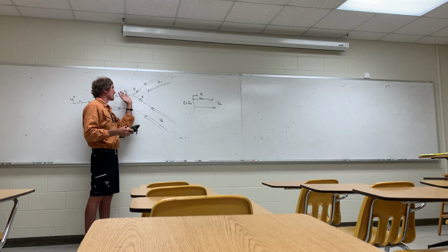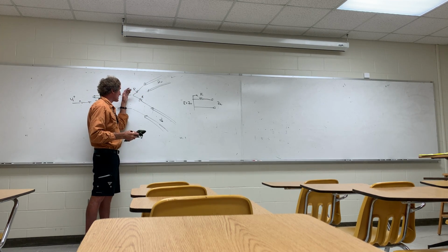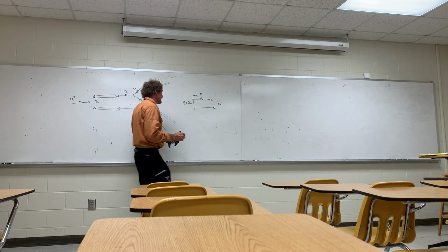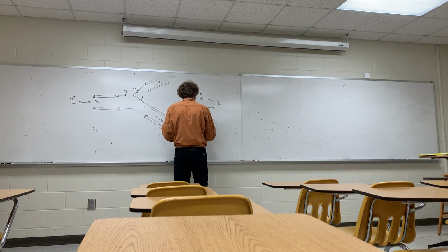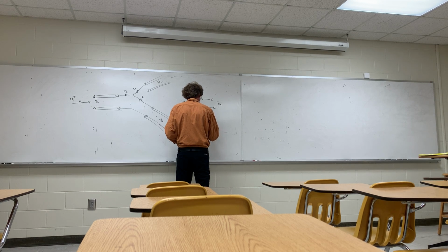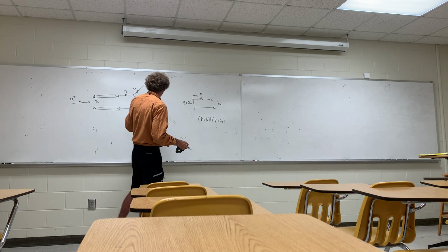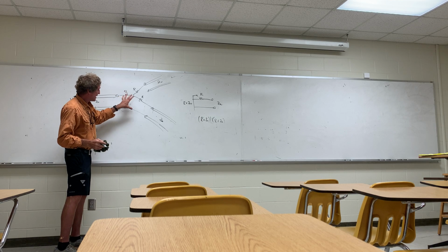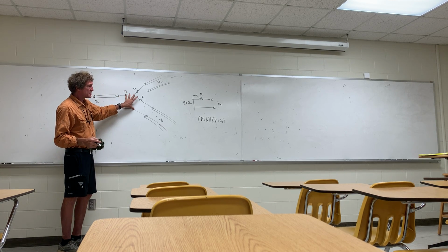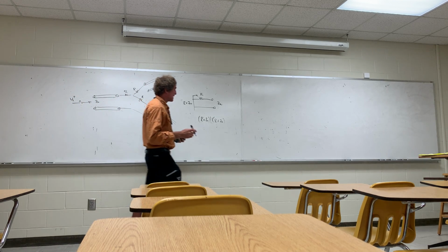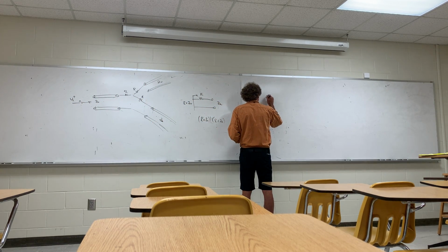I look from here that way and I have R plus Z naught, and from here that way and I have R plus Z naught. So that means I have really R plus Z naught in parallel with R plus Z naught. Or it's really the input impedance at this point, looking that way for these two ports, is just R plus Z naught divided by 2. Make sense to everybody? So I have R plus Z naught divided by 2.